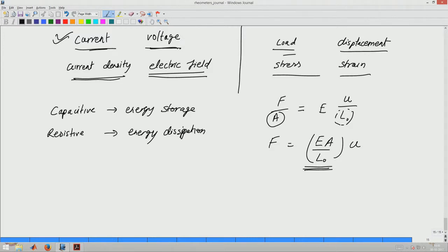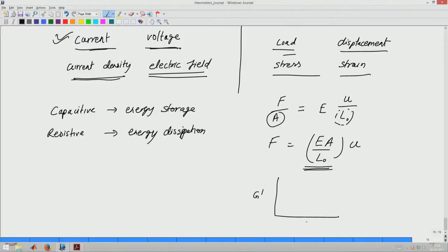So, for example, just the way we saw that the basic primitive model for viscoelasticity was the Maxwell model, which said predominantly viscous response at low frequencies and then elastic response. Then we saw also the standard linear solid model, which was elastic response, which was rubbery, and then elastic response, which is glassy. So what we saw was G prime as a function of frequency was something like this. At very low frequency you get rubber elasticity, at very high frequency you get glassy elasticity, and G prime varied like this.